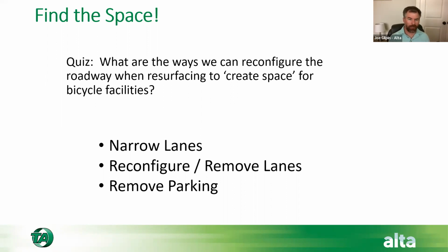How are you looking at your capacity? So I look at capacity. I look at parking utilization. I'm looking at the size of my intersections and how they're being controlled, and are they driving the need for more lanes because we're not using the roadway as efficiently as possible. So there's a lot of efficiency that we're thinking about when we're trying to find more space to serve all user types. And a lot of the projects that we do work on, we may be able to even maintain our level of service goals for cars at the same time that we're able to do more for people walking and biking.